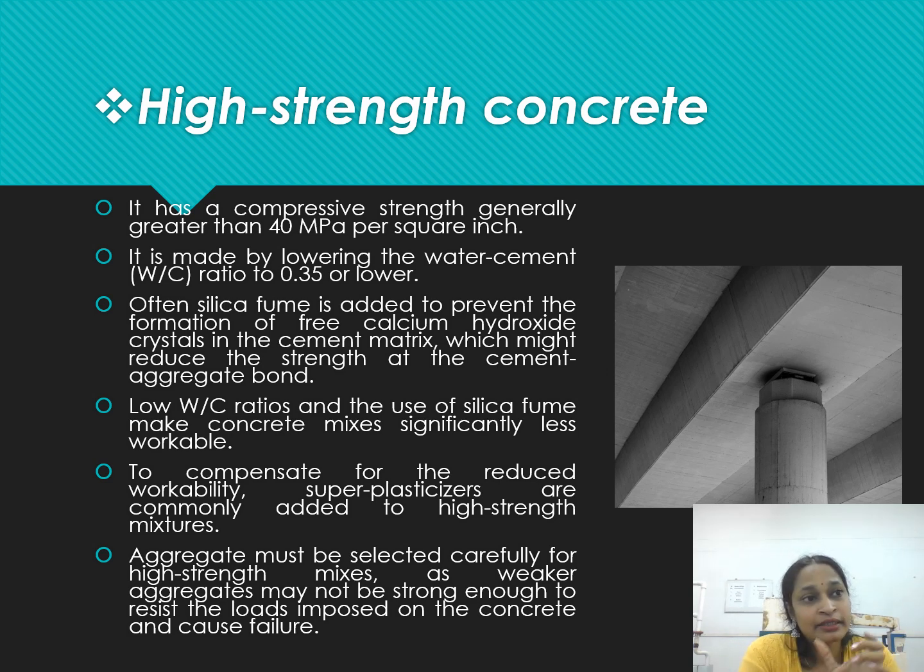In that time you should be able to give the desired shape you want to give to the concrete. So that is the workability. This can be altered using some super plasticizers, admixtures. These also sometimes add strength.